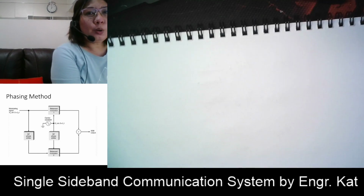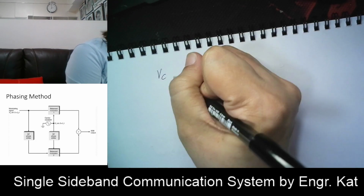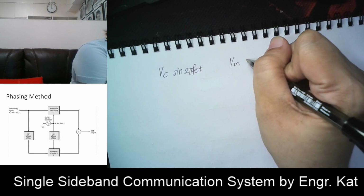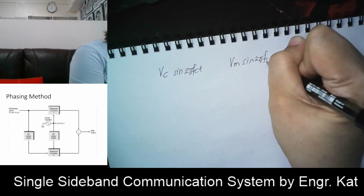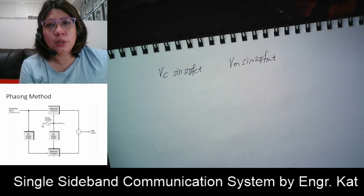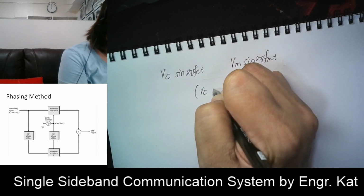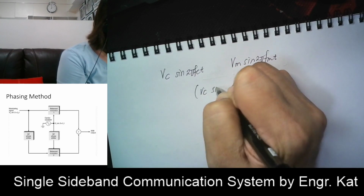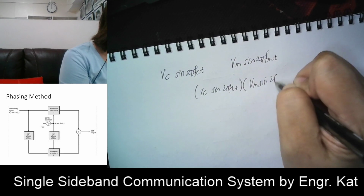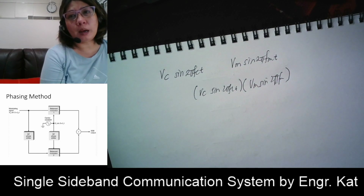As you can see, you have two inputs, the carrier and the modulating signal. Our carrier is Vc sine of 2 pi fc t, and our modulating signal is Vm sine of 2 pi fm t. The output of our balanced modulator is equivalent to the product of these two, which is Vc sine of 2 pi fc t times Vm sine of 2 pi fm t. This is the product of balanced modulator 1.